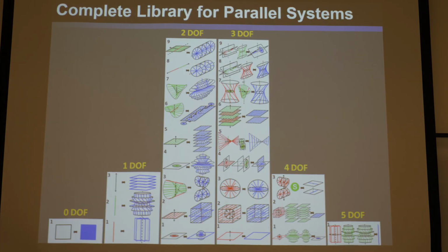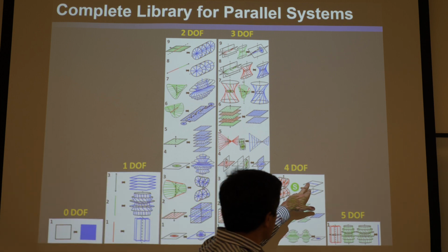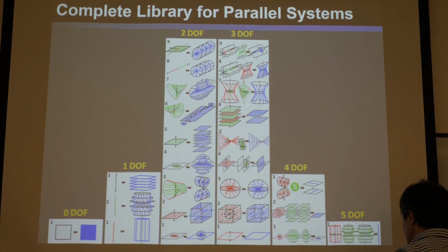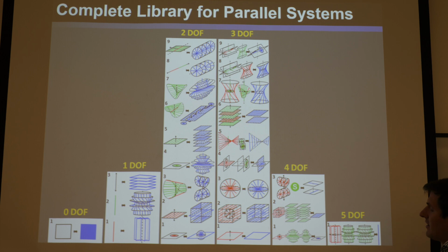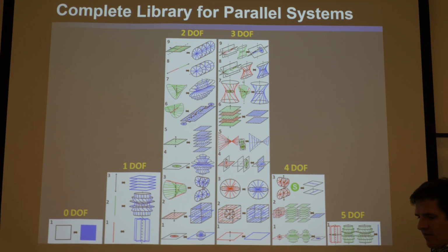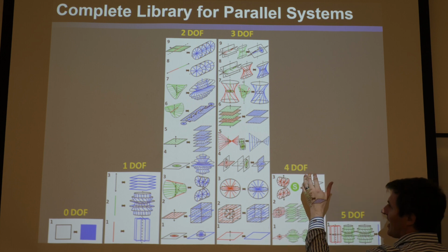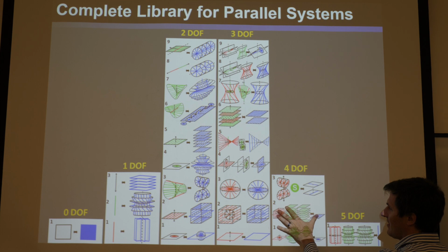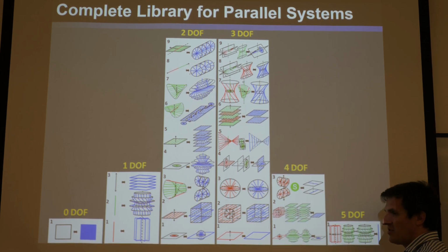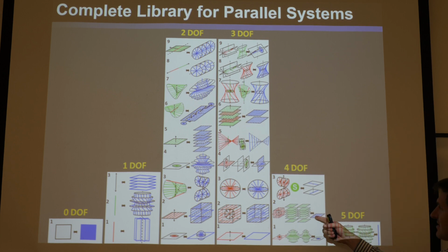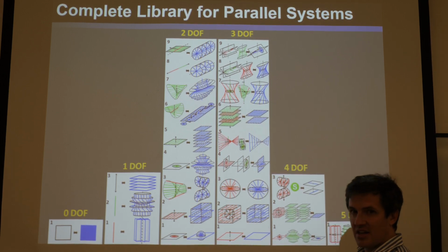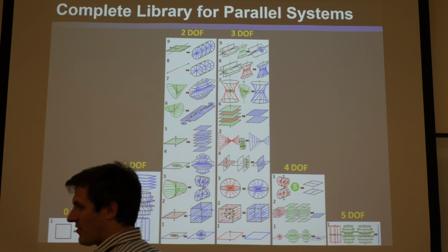then it turns out, and you can see its constraint spaces right there. So then it turns out that if you take a random potato of any shape and stick 2 wires in it, they're either going to be this freedom space if they're parallel, this freedom space if they intersect, or this freedom space if they're skew. And the skew angle, the distance between the parallel lines, the angle between the intersecting things, doesn't matter. They're the same freedom constraint space type.